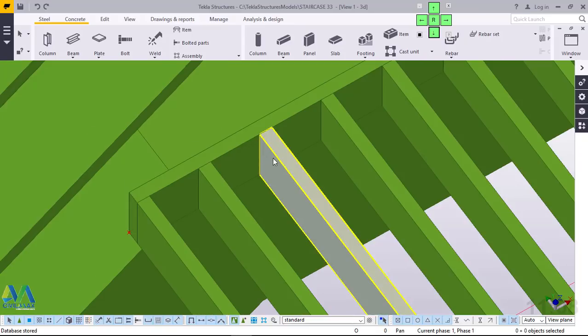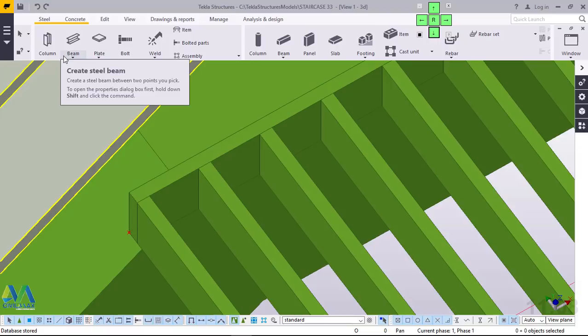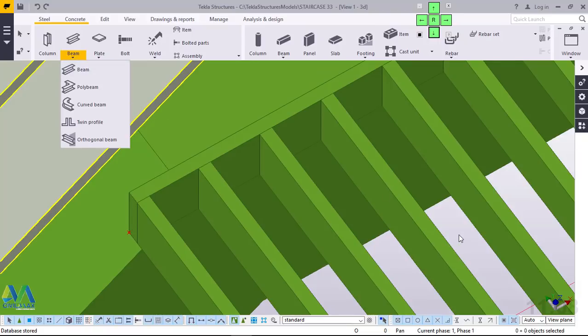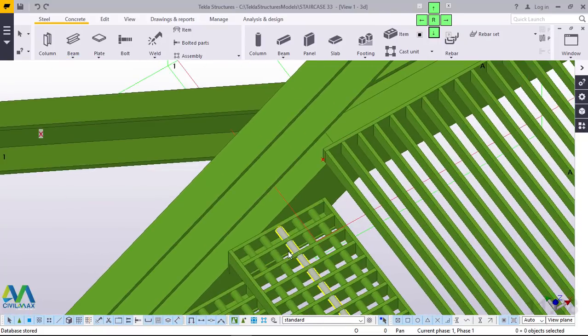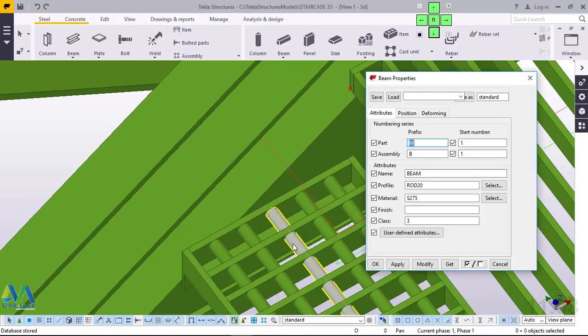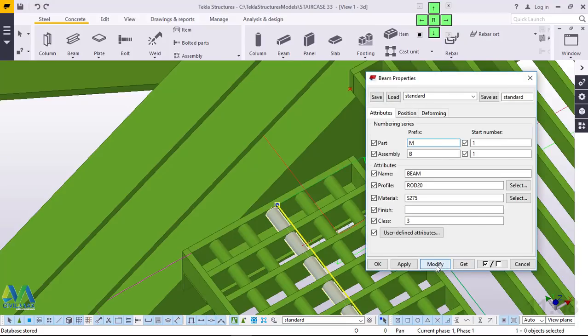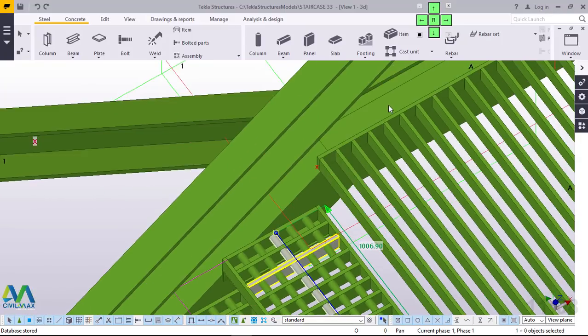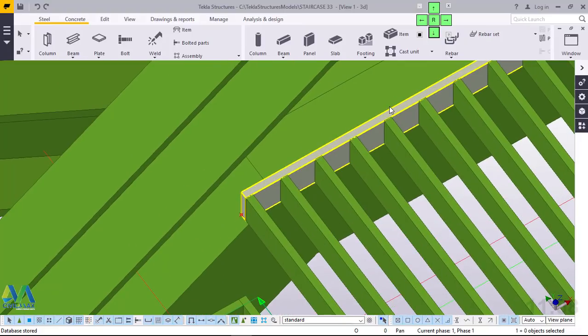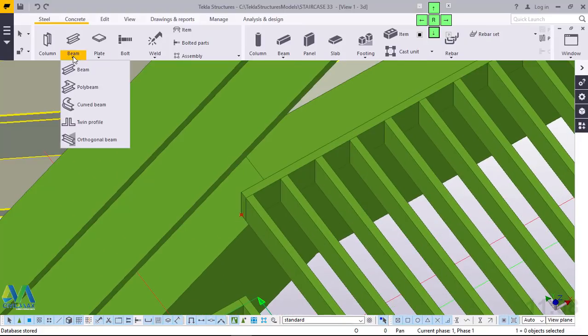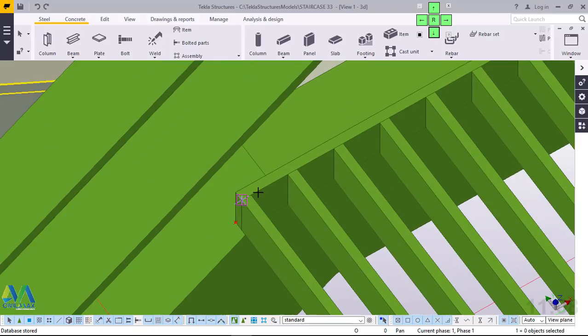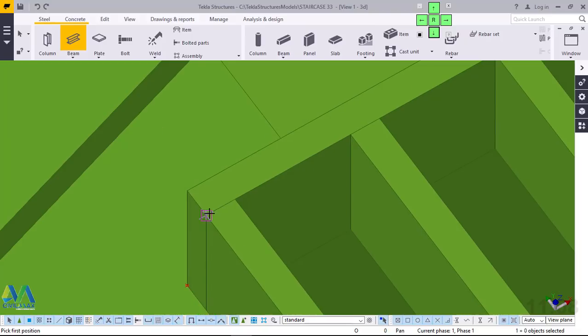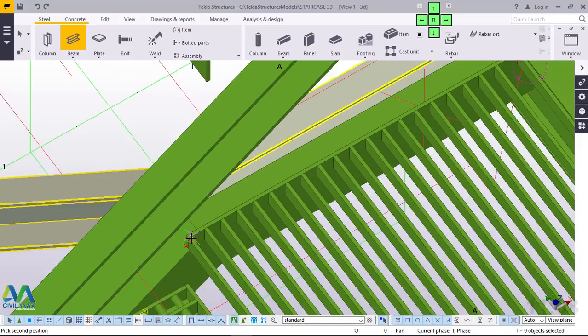Then we'll come to this end. We'll come to this member and double click on this circular section member, then click modify, apply and accept, just to default on it if we intend to create a steel member of the same size. So instead of feeding the dimensions, that will be our default steel member creation. Then I'll snap right here, and run all the way to this end.